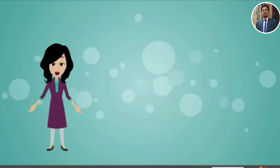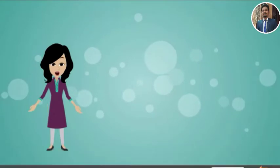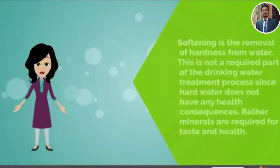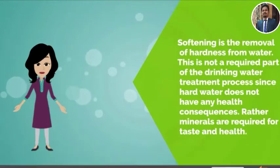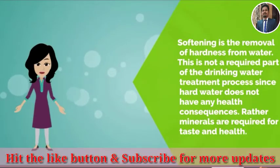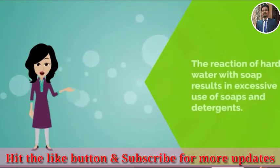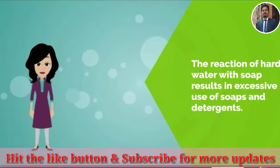Since it is important to remove hardness from water, we opt for the water softening process. Softening is the removal of hardness from water. This is not a required part of the drinking water treatment process, since hard water does not have any health consequences. Rather, minerals are required for taste and health. In addition to being unsightly, the reaction of hard water with soap results in excessive use of soaps and detergents.